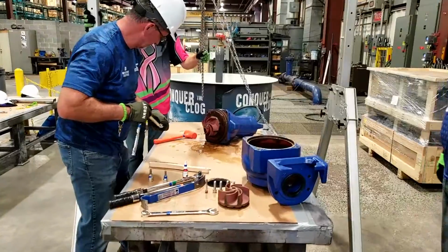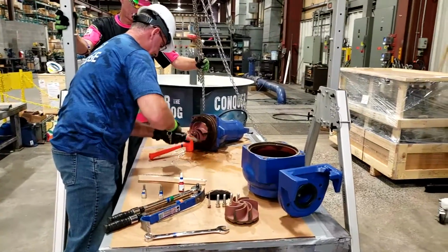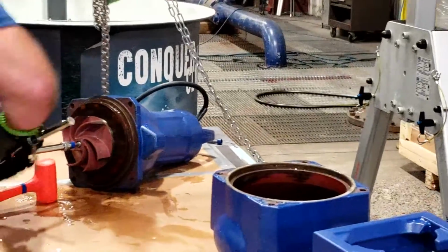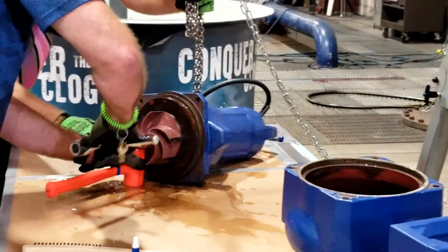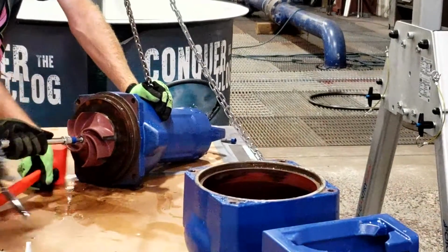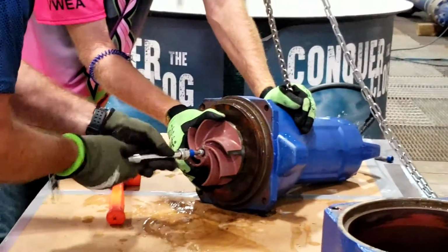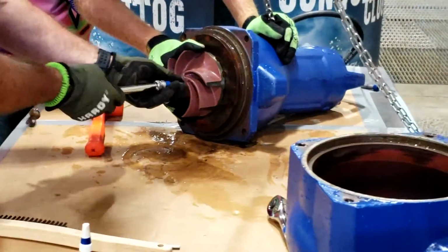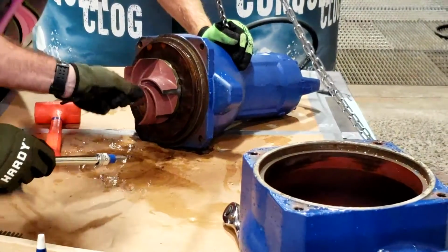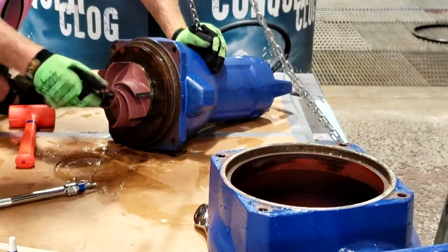You must use the dead blow hammer to block the impeller when removing the bolt. The individuals handling the impeller at any time must be wearing leather gloves. To remove the impeller, utilize the 8mm impeller jacking bolt by threading it into the shaft and tighten until the impeller is released and can be safely removed. The jacking bolt must be removed from the impeller and placed back in the toolbox at the conclusion of the event.